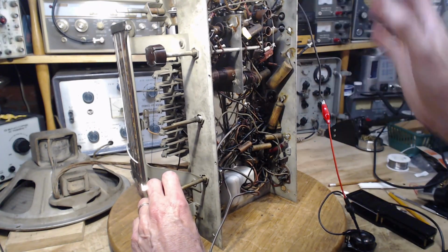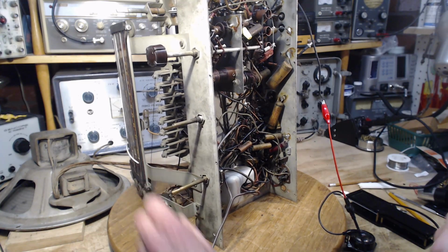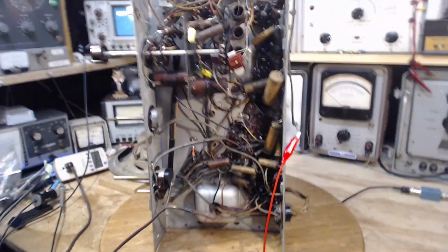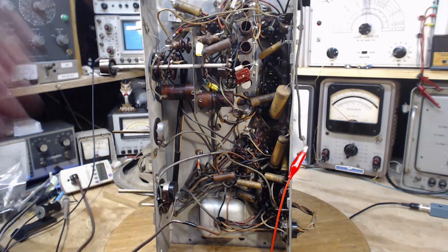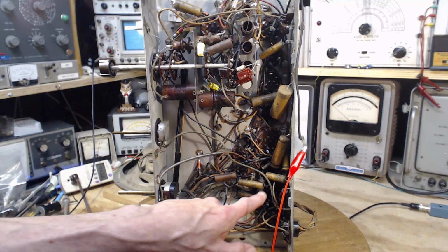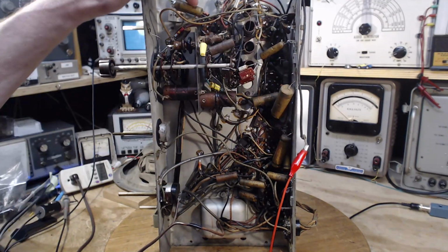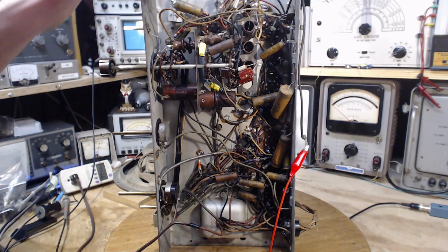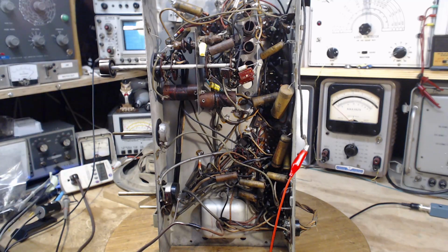Well, piles of bad capacitors still in here. Okay, so that did solve a big problem, I think, but it didn't solve all the problems. And again, we probably have kind of general degradation in here because look at all the wax capacitors. 1, 2, 3, 4, 5, 6, 7, 8, 9, 10, 11, and one hidden down, so 12. There's a dozen of them in here. They all got to go.